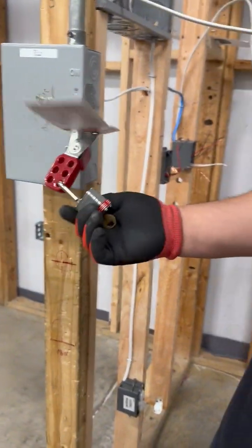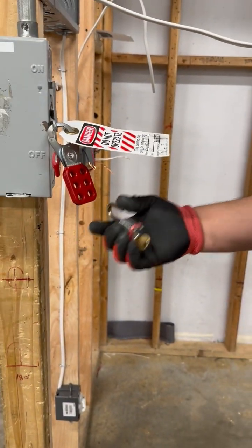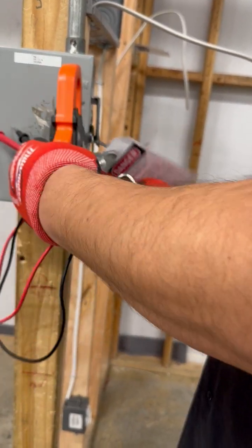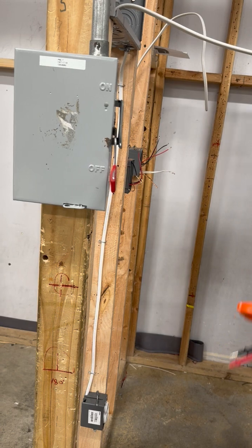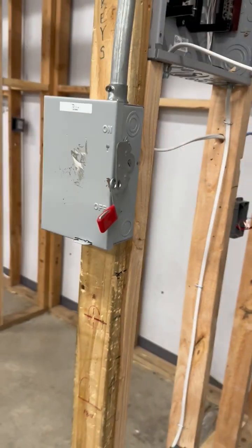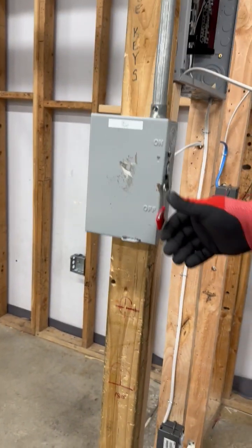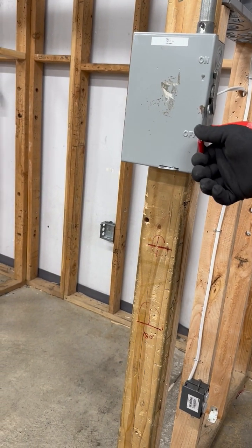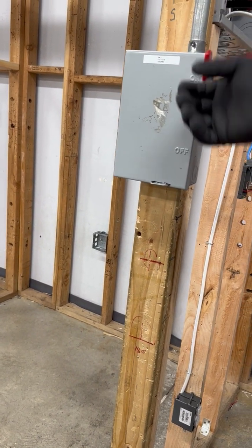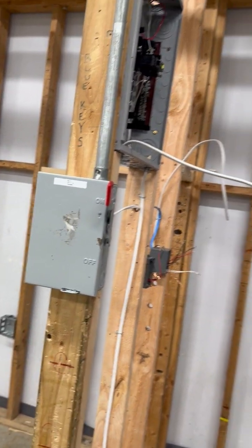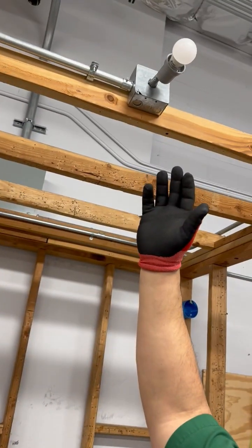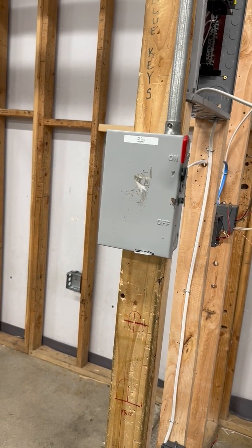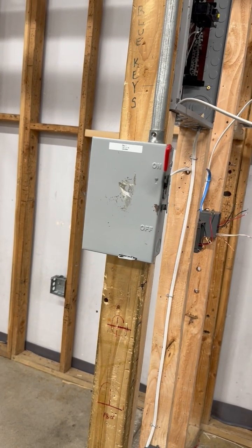When it comes to lockout tagout, we have to take the advantage of explaining the importance each time we open up these disconnects. Explain and make sure that they know what the disconnect is and how to check the power of the disconnect if we have any troubleshooting issues. I illustrate to them: keep the door closed, keep your distance, energize. Did we get a light bulb? If we didn't get a light bulb, the light bulb could be out. That's now another troubleshooting effect. Or the circuit breaker is de-energized.